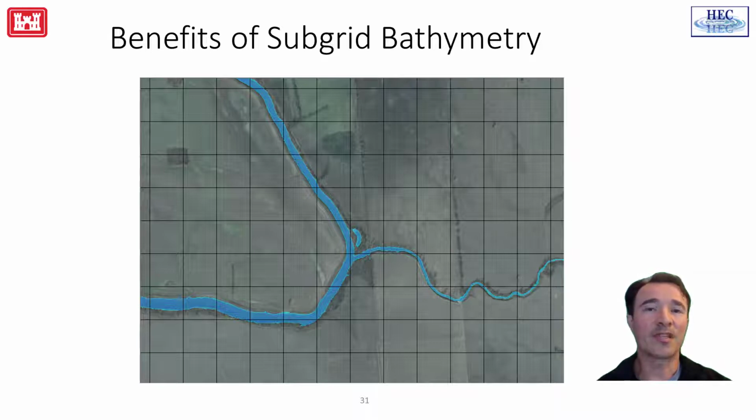In this type of example, flow can move through a cell or channel in a 1D type of mode, while flow in the overbank areas will be 2D from cell to cell. If the user wants more detail within the channel, such as 2D flow velocities and varying water surface elevations, then smaller cell sizes can be easily specified within the channel. However, if the goal is to convey water through the channel and capture the 2D flow in the floodplain, this is a very good option.